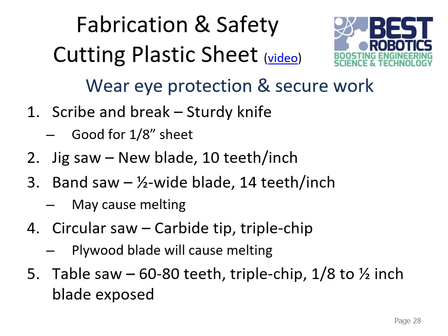You can use a bandsaw or a circular saw or a table saw, and similar things apply for all these. I won't go into too much of the details here, but it's here for reference. Just know that with some blades, when it's going really fast, it can actually melt the plastic as it cuts. It's not necessarily a bad thing. Just be aware of that.